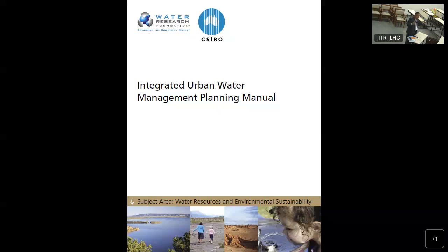And also we can have similar options for industrial, where that water can be utilized depending upon the type of industry and the type of application of the water there. Similarly, we can think of providing an integrated water management system for commercial, such as multi-story shopping complexes. There are a number of toilets there. The supply can come through alternative water supply sources. They can have their own larger rainwater tank system. So this is the basic concept which talks about integrated water management.